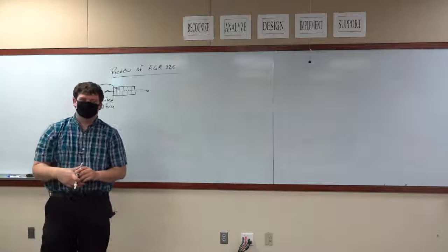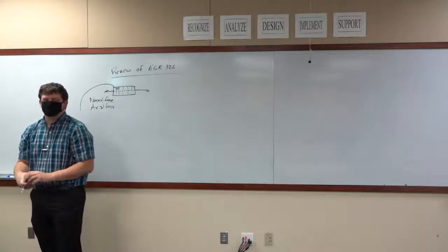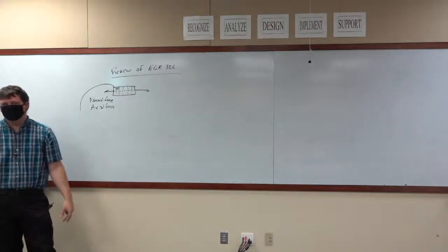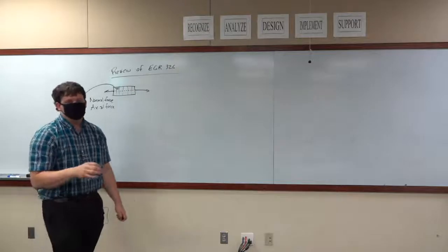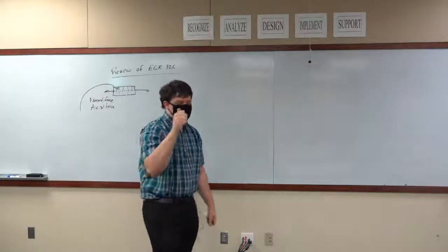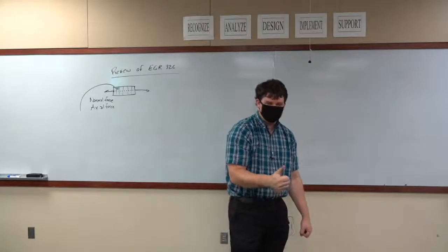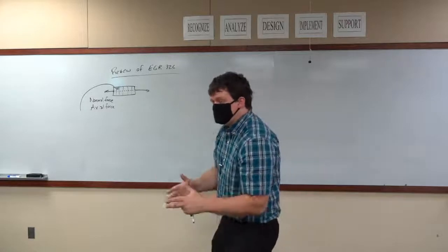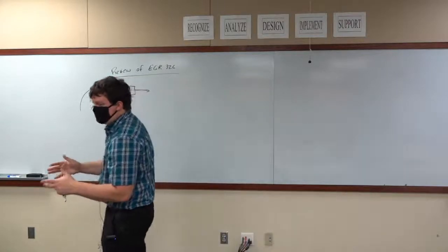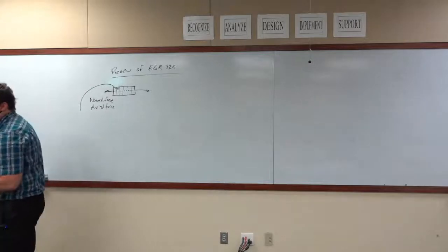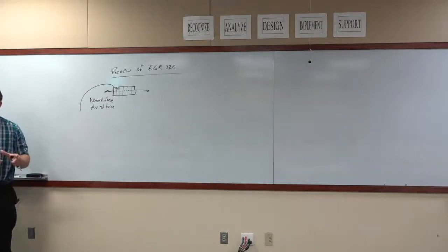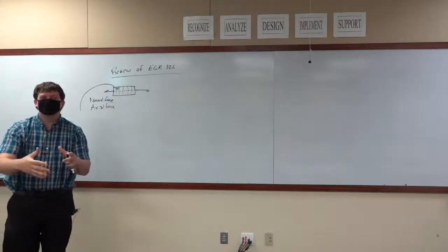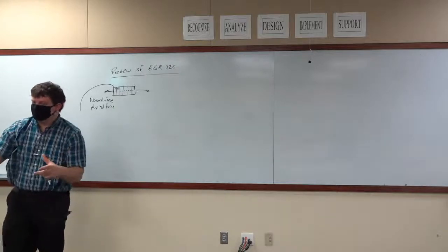It's called a crash cushion. That is intended to fail in front of your vehicle. As you smash into it, the whole thing deforms, fragments, and shoots things out of it. It has been carefully designed so that it fails in a controlled manner, such that, first of all, none of those materials fly through your windshield, because that might kill you. Second, so that it actually does absorb the energy of your vehicle. Otherwise, it's not doing anything. And third, so that it provides sufficient deceleration so that you can slow down in a quick enough distance that you don't hit whatever it's trying to protect you from.